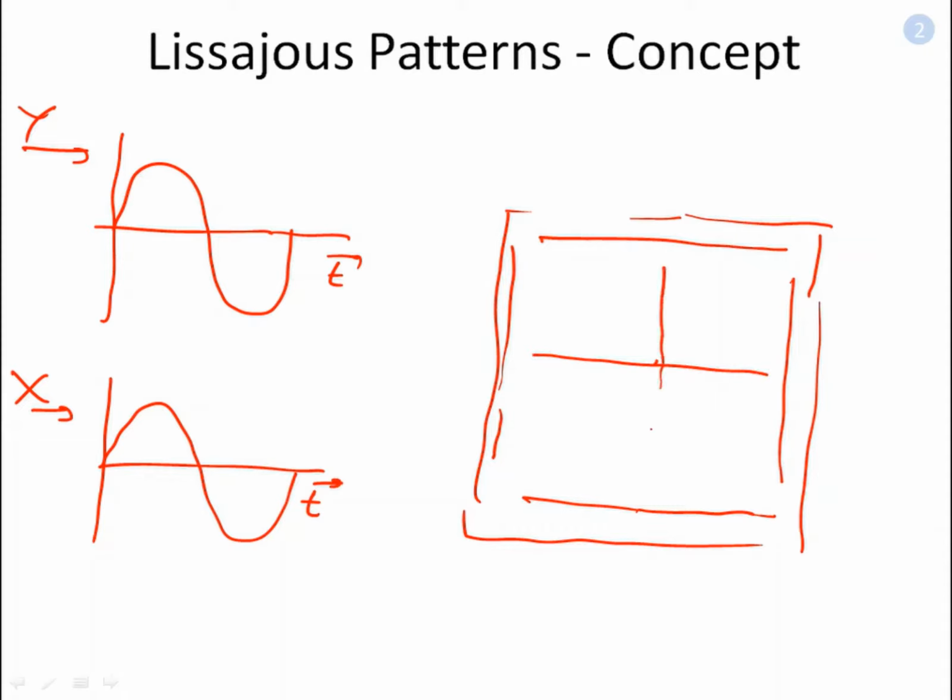I draw two lines at normal just to trace how the signal is changing. So suppose at some time t1, both the signals have this magnitude. So this is on the positive side of the Y plate, maybe this point, and this is on the positive side of X plate, maybe this one.